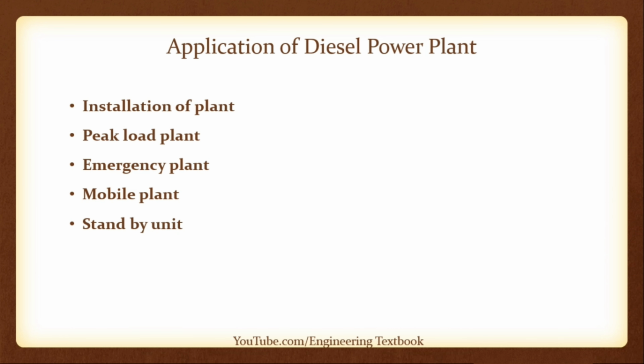Standby unit. This plant can be used as a standby unit with a hydroelectric power plant. When the water is not available sufficiently in the hydropower plant to meet power demand, the diesel power plant operates in parallel with the hydropower plant.